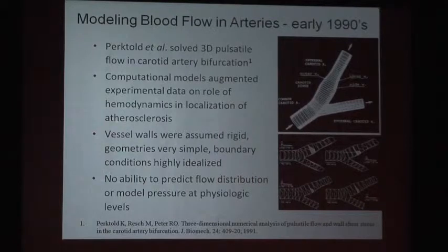Our previous speaker spoke about the importance of the outflow boundary conditions, and for us in the circulation, we have pressure and flow waves going through our arteries at any time. If we want to abstract part of the circulation, take the large arteries for instance, we have to pay attention to what's upstream and what's downstream, because there's no way to predict flow distribution or pressure if you don't pay attention to that.